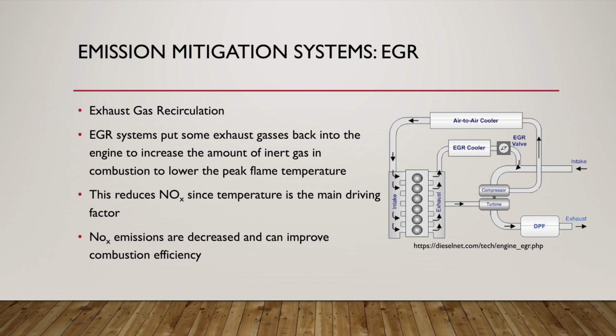And the reason we're doing this is because we want to lower the temperature so that we have less NOx production, because NOx production is based on the temperature. So the higher the temperature, the more NOx production we are going to have. If we can put that exhaust gas back into the intake, that means we can burn it again. So if there is unburned hydrocarbons, we can get a little better combustion. And then also, the emissions are going to be decreased because the temperature is going to be lowered. And we don't want to have as much NOx emissions because NOx is bad for you, and we don't like that.